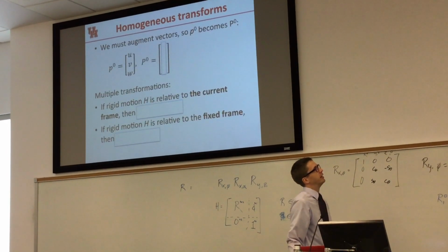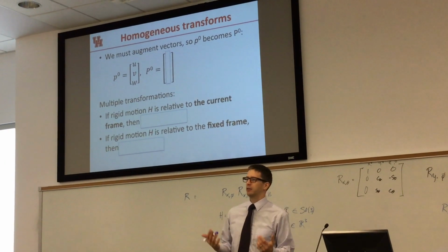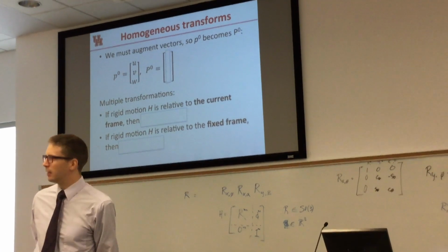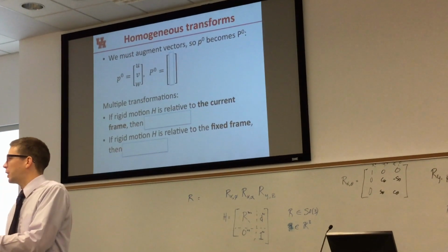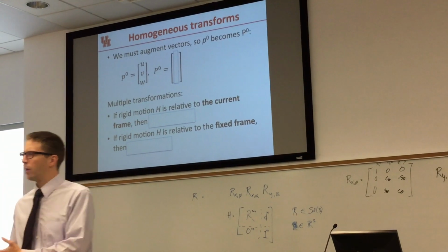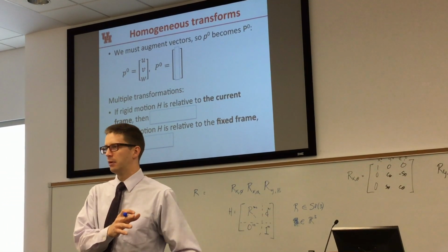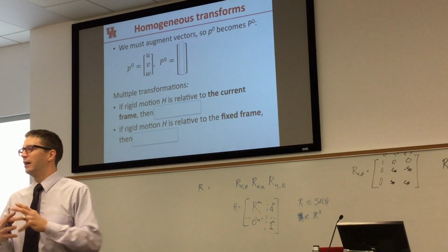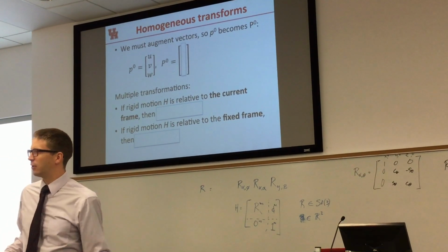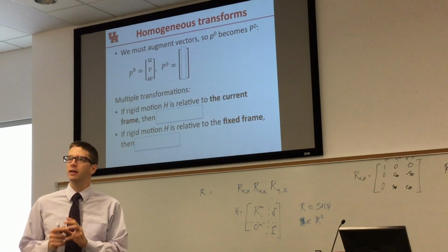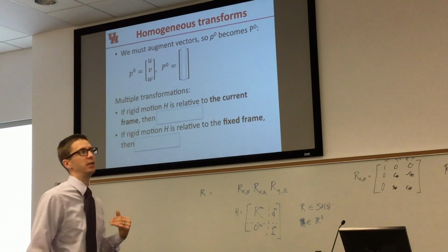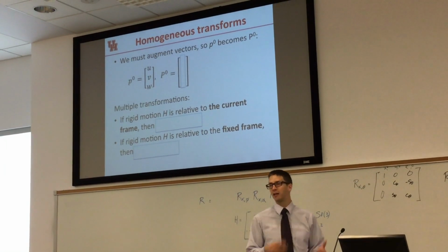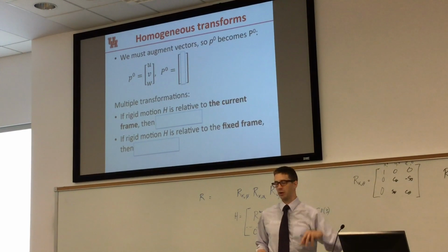And so what we want to do is, if we want to work with vectors, we can think of our robot as a point cloud of 1,000,000 points. And when we apply some homogeneous transformation, we want to say, well, where is that point cloud moved to? The constraints that we're applying to this means that our robot will not expand in any direction. We're not stretching it. All we're doing is rotating it and translating it. That's what makes it a homogeneous transformation. It's not going to gain any more volume. The point cloud will still have the same volume. It'll just be moved to a new location.